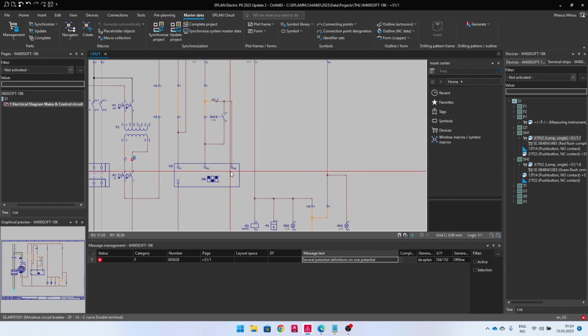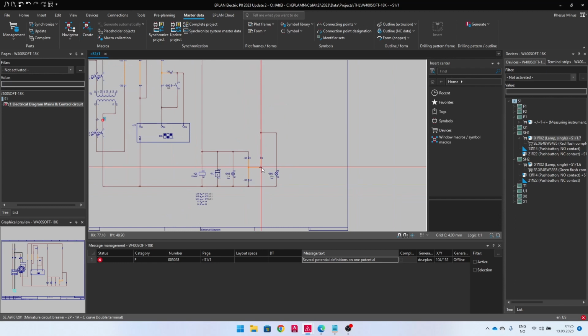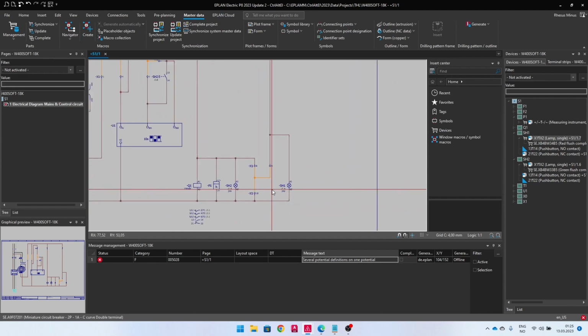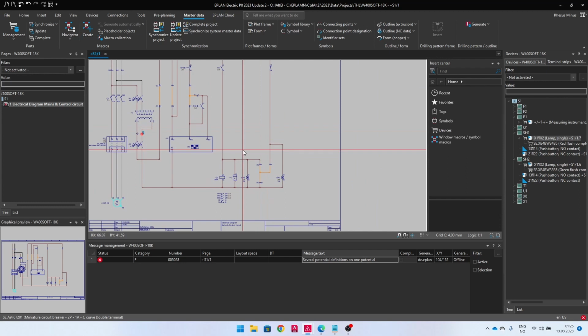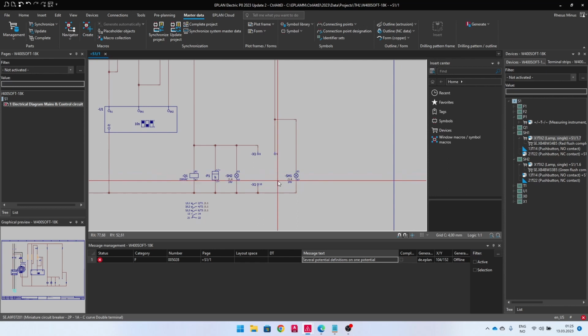And I have a short circuit somewhere. And I guess you can all see that one. That would be, of course, here. These are connected directly together. I guess I must have misread the schematics somehow. Now, of course, these should not be jumpered together. These are for the lamps. So these should not be jumpered together when you don't have the remote panel like this.